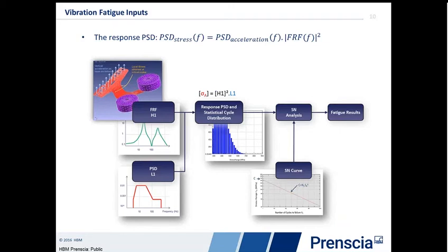One comes from the finite element model, and it's called a frequency response spectrum. It's a transfer function. Basically, it specifies that at some load input on my model, these are the outputs that I would see over a frequency range. It's a frequency response function that allows me to capture the dynamic aspects of the model. This frequency response function is calculated inside of your finite element analysis as either a steady state dynamics or harmonic solution, or solution 111.